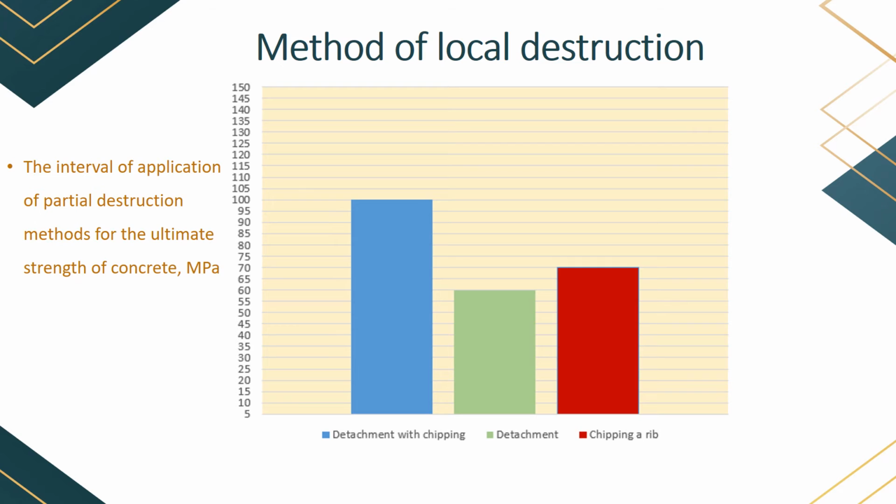One of the most common methods used to determine the strength characteristic of concrete is impact action methods. The methods of impact pulse, elastic rebound, and plastic deformation are based on the principle of determining the concrete strength through impact pulse action on it. The basic principle for each of the above-mentioned methods of impact action is the interaction of the pulse delivered by the impact device's striker and the structure material.